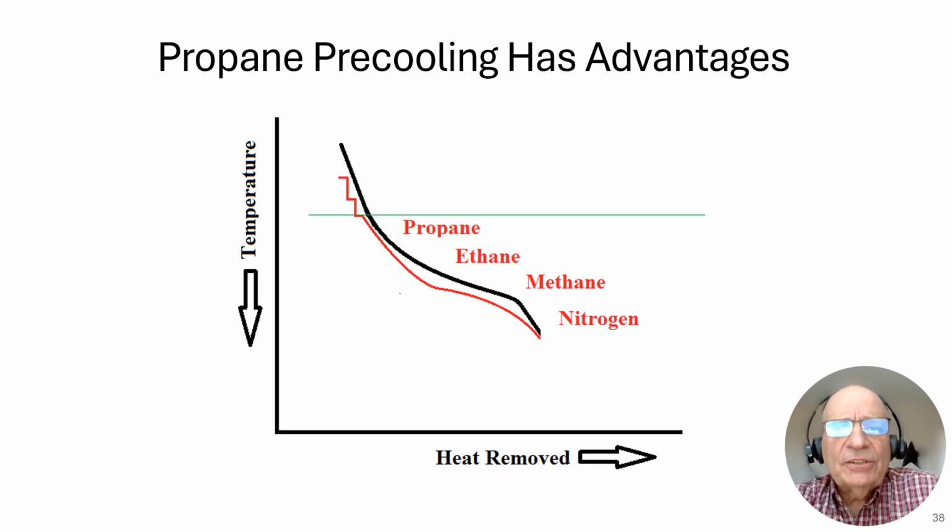On the earlier slide, I mentioned that we're going to be pre-cooling the MR in order to get it to separate to MRL and MRV, but it also pays to pre-cool the feed gas that's coming in. You could use an MR system, or you could use a propane pre-cooling system, and each of them has their unique advantages. This diagram shows a propane pre-cooling system associated with your MR system. You see this one's showing 3 stages of propane cooling, one here, and one here.